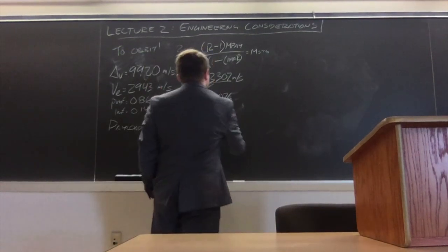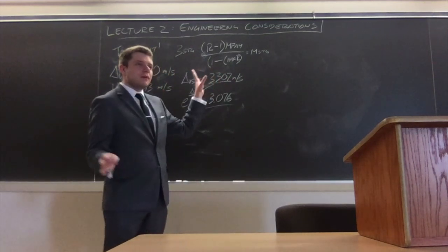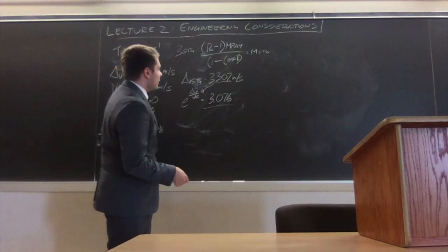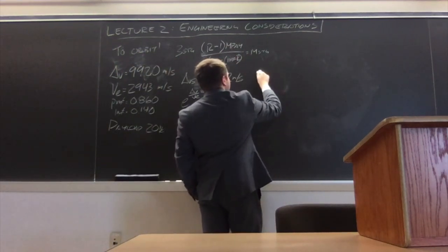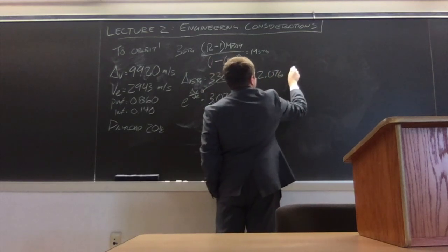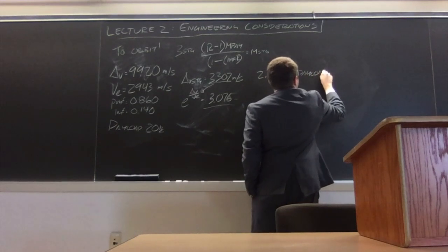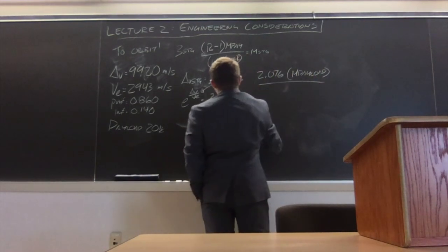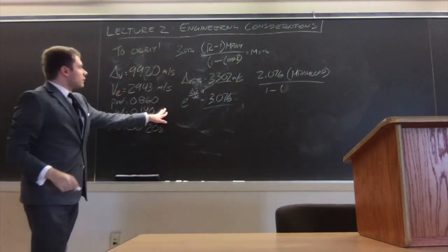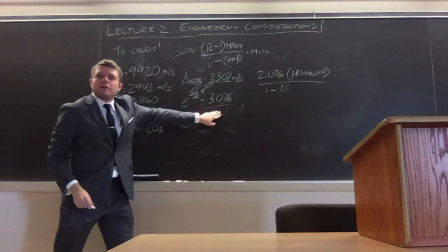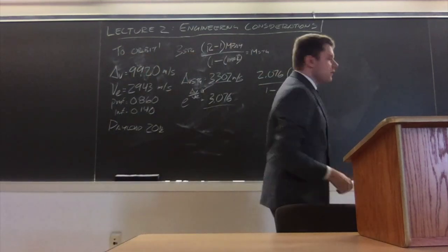Good. Okay, so we have a value of 3.076 for each stage. That means we can basically use one equation for this entire thing. We have the numerator, which is just r minus 1, so that's 2.076 times the payload mass, over 1 minus the inert mass fraction times r. And if anyone wants to run through that, I'll just spoil it and tell you: it is 0.4364.